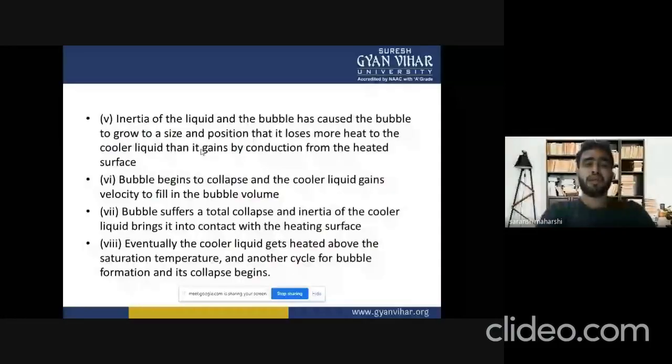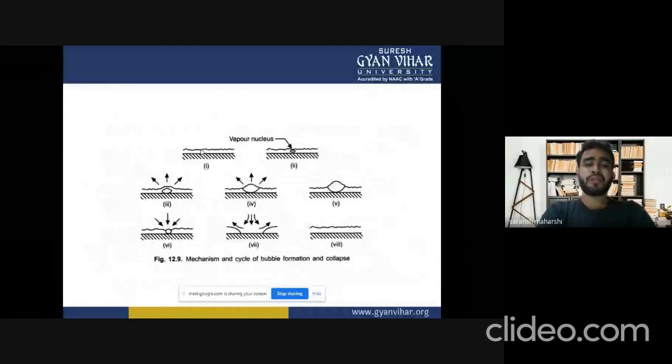Nucleate boiling is thus characterized by the motion of bubbles at the nucleation sites and the resulting liquid agitation. The bubble agitation induces considerable mixing and promotes a substantial increase in the heat flux and the boiling heat transfer coefficient.